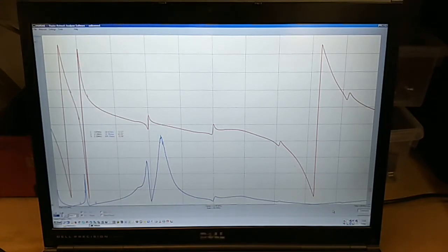So obviously the overall effect from an impedance point of view is when those 4.7 nanofarad tanks are in series, effectively we're looking at a 2.35, or roughly 2.3, 2.4 nanofarad series capacitance, which is connected to the parallel resonance circuit of the primary. So in other words, we've now got 3 resonant circuits interacting in this system.